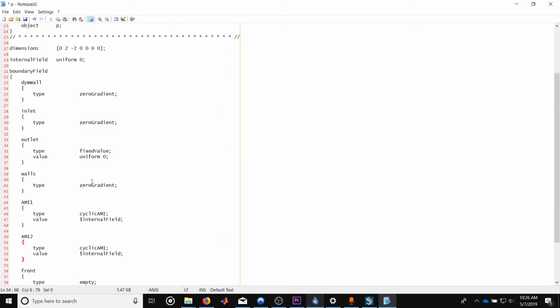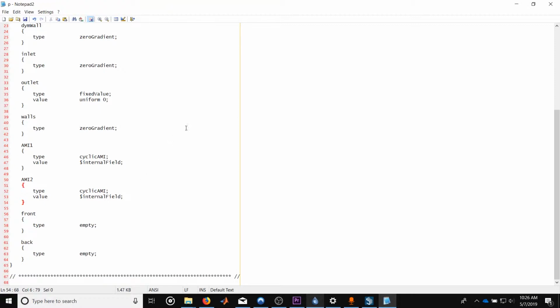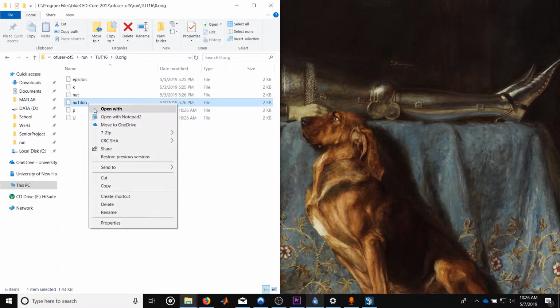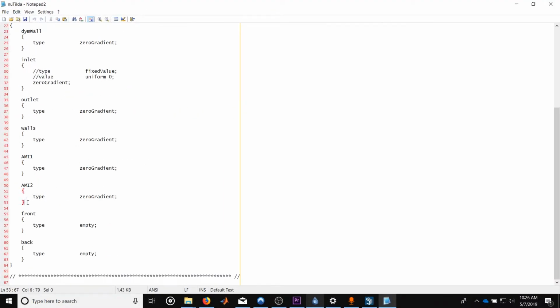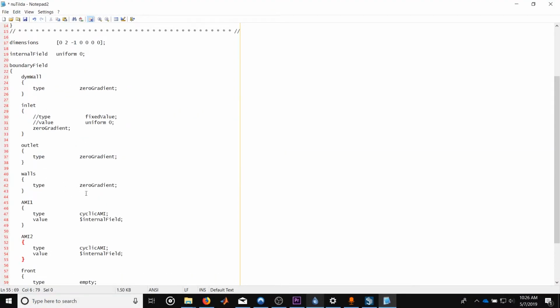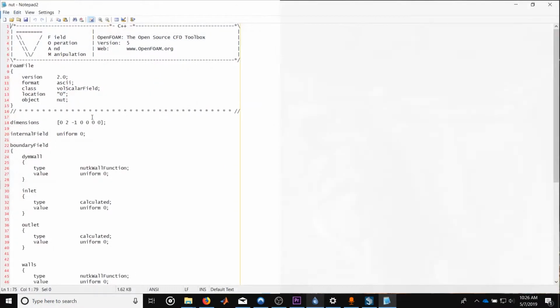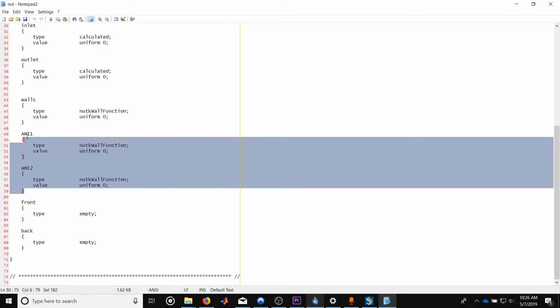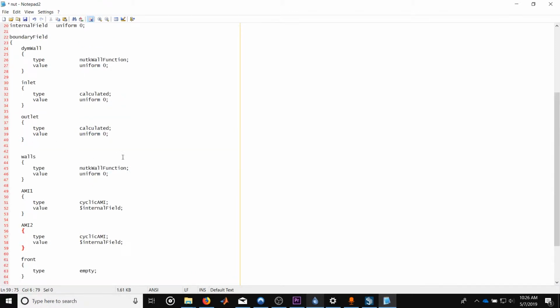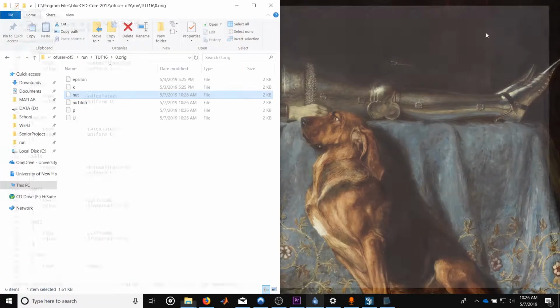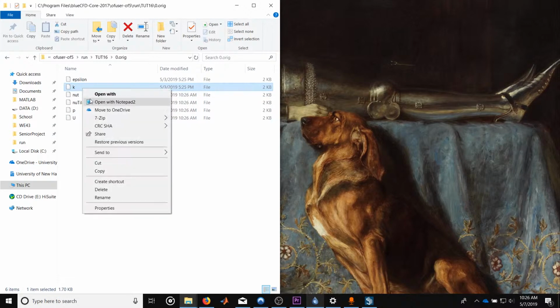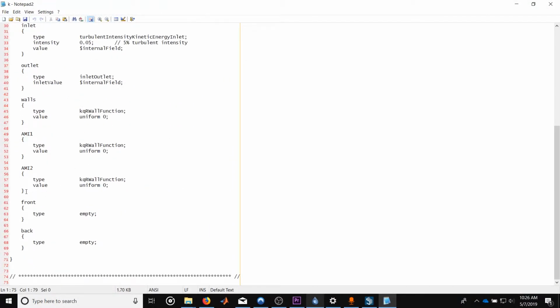And since it's all the same, we can just copy paste this exact same boundary condition on pretty much whatever kind of variable you're using, whether it's pressure or nu or k-epsilon, k-omega, k whatever. Unless you want to enforce some sort of difference, like a pressure difference over the AMI, for our purposes it's always going to be internal field.